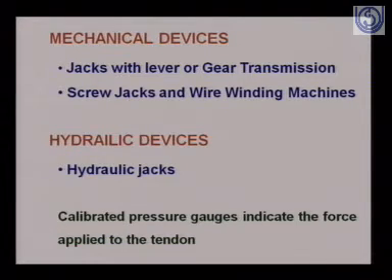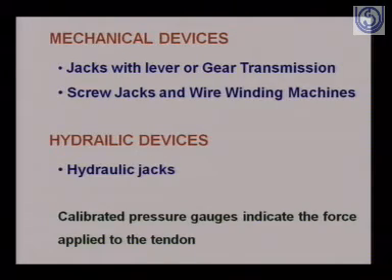Because here the stresses are induced or generated in a strand. Strand, you understand? Strand is a rope type of thing of steel in which there are many wires of small diameters. So it is a steel rope type of thing made of a number of wires of small diameters. So that is called a strand. In some cases, in the pre-stressing process, we use a single wire of large diameter also, but generally strands are preferred.